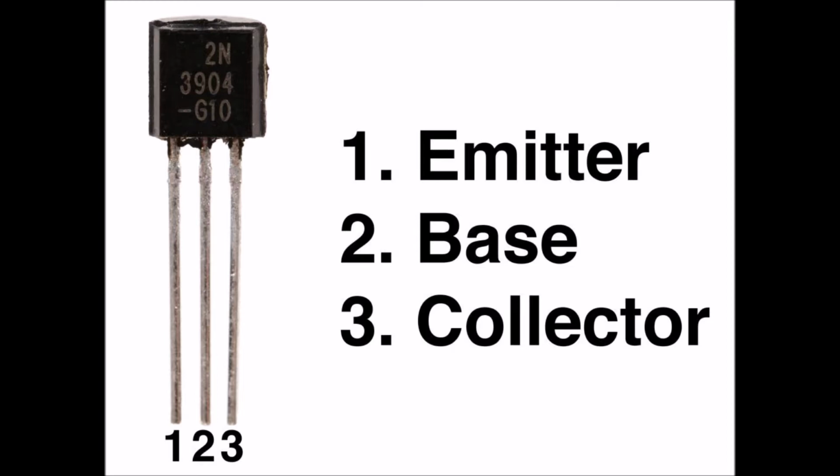Overdrive. Even when we bias a transistor so that it can produce the greatest possible current amplification at or near point A in figure 22.6, we can encounter problems if we inject an AC input signal that's too strong. If the input signal amplitude gets large enough, the transistor's operating point might move to or beyond point B, off the coordinate grid, to the left, or both, during part of the signal cycle. In that case, the effective value of beta will decrease.